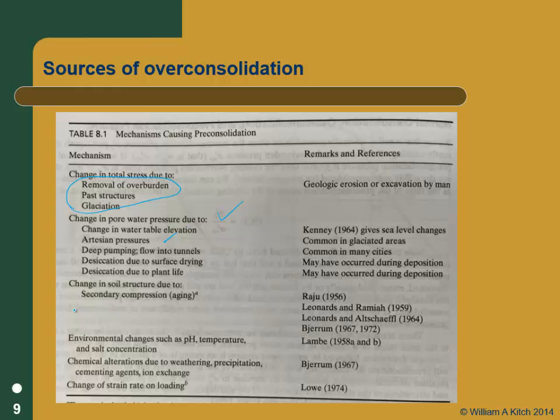Soil aging, this is the one I was just discussing, is that even normally consolidated soil is going to undergo creep and secondary settlement after it's deposited. Another way to think about it, it's going to develop its own structure, and that's going to generate some stiffness that, once you overcome that structure, it's going to be softer. So even normally consolidated soils normally have a small preconsolidation stress.